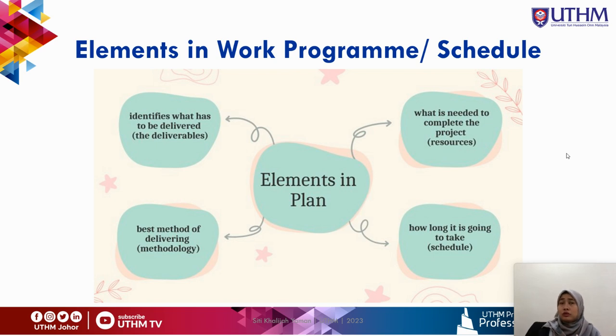Maybe you have to look into other technology to construct that building. That will involve time and also cost and resources. So you have to know which delivery method to use to deliver that project. You have to plan it ahead, and how long it takes to complete. If you are using the conventional method, you need to know how long it takes, and you have to consider everything: the installation, the weather, the curing process of the concrete, and so many more.